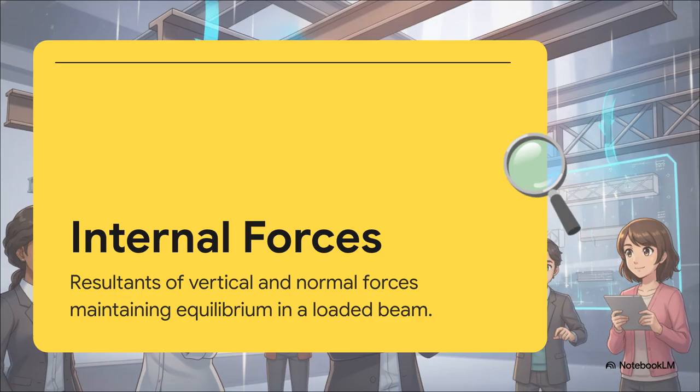Instead of getting bogged down in dense textbook definitions, let's just visualize it. Shear forces, they're basically like a giant pair of scissors trying to slice the beam right in half vertically. Bending moments, on the other hand, are more like grab a pencil in both hands and try to snap it by bending the ends up or down. Drawing shear force and bending moment diagrams is literally just the process of figuring out exactly how hard those scissors are slicing and how hard that pencil is being bent at every single millimeter along the length of the beam.